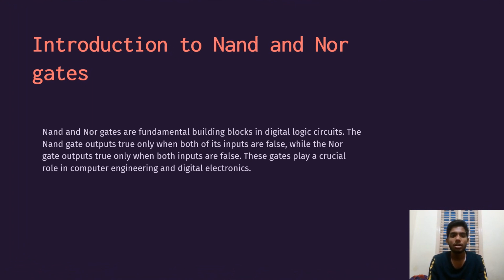Introduction to NAND and NOR gates. NAND and NOR gates are the fundamental building blocks in digital logic circuits. The NAND gate outputs true unless both of its inputs are true, while the NOR gate outputs true only when both inputs are false. These gates play a crucial role in computer engineering and digital electronics.